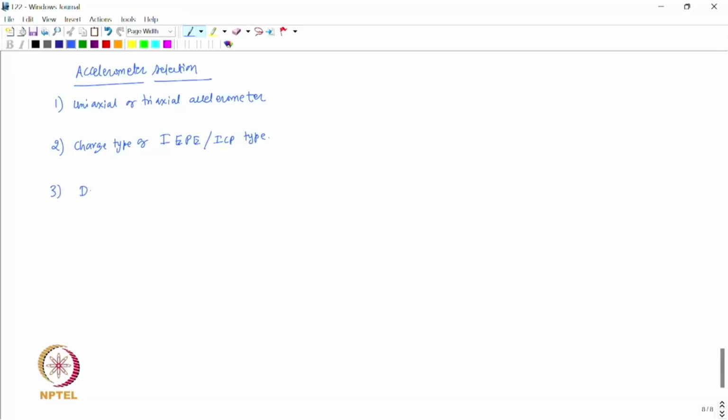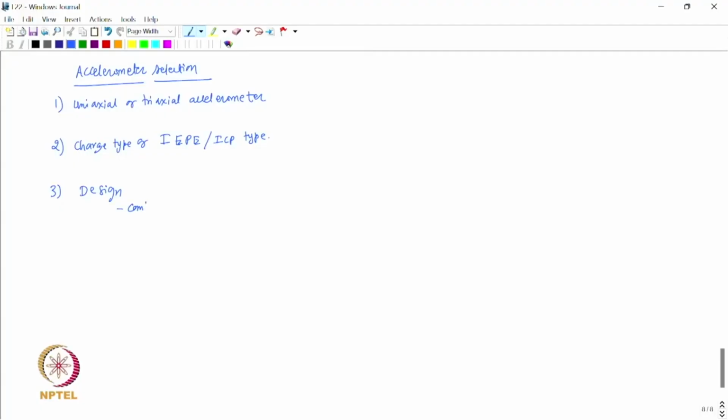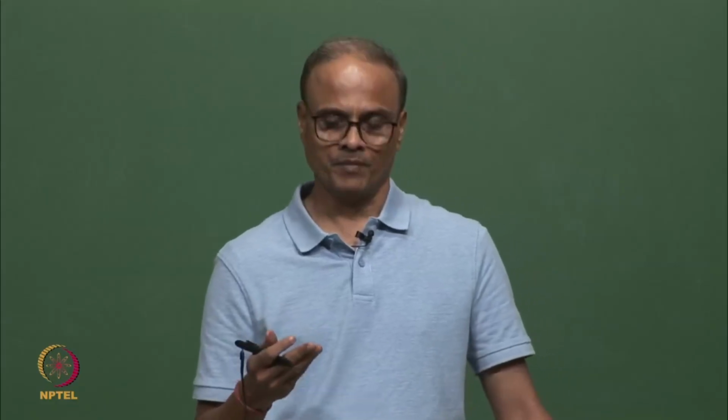Then the design. Design basically refers to how the piezoelectric crystal is arranged with respect to the seismic mass. So, there are several designs available like compression, then we have shear design, we have flexure design. So, let us look at compression and shear designs. In the compression design, the piezoelectric crystal or the disc is under compression.